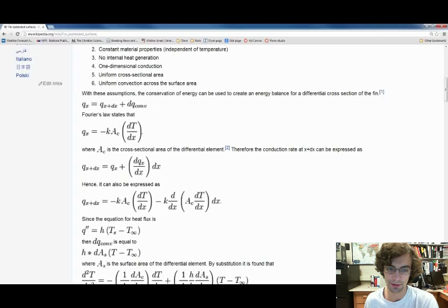However, the thing you'll know about this is they treat this as one-dimensional conduction, which, if you think of it, cannot be true, because if we're having convection to the ambient, then there must be heat transferring radially through the fin. And so that would imply that there should be some partial T, partial R terms in here, that there's a variation, that temperature is a function of R.